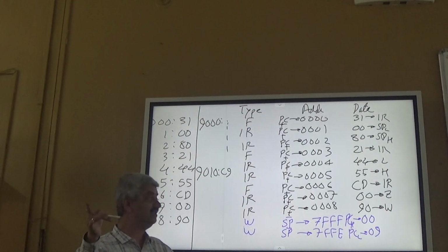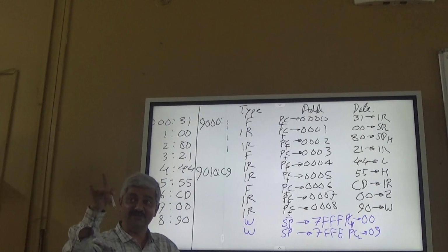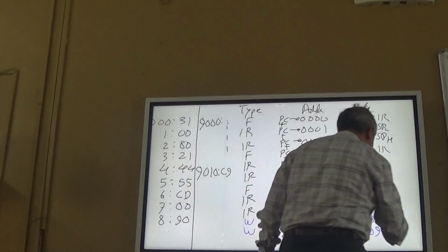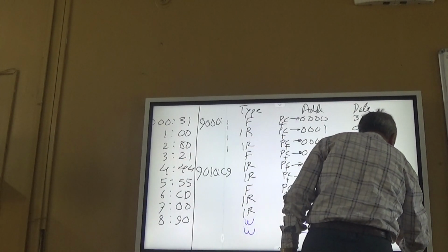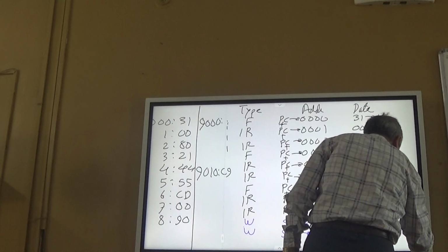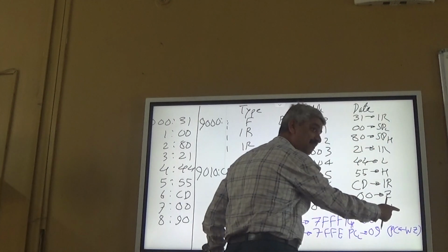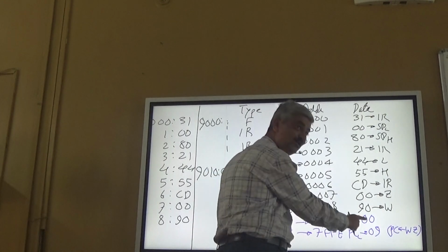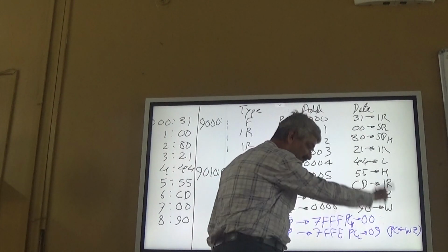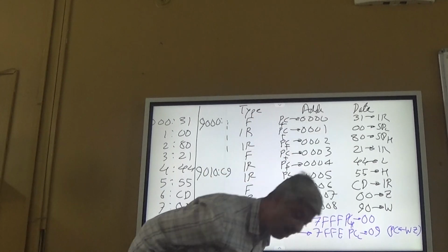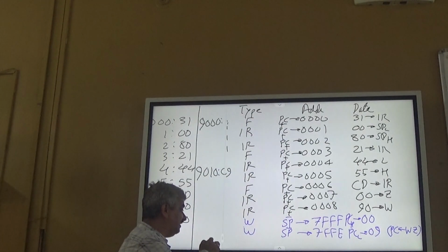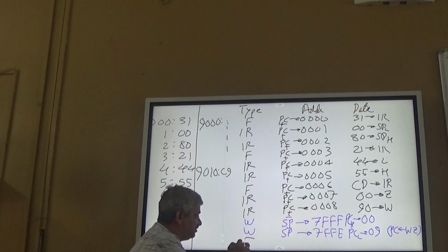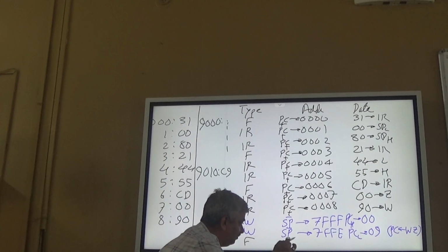Now what? Program counter assigned to WZ. Why now? Because if it happens earlier, then 0009 will be lost. So 0009 is stored first, then program counter assigned to WZ. It means what? In the next cycle of code fetch, what will the program counter give?